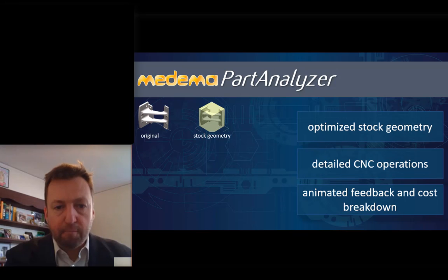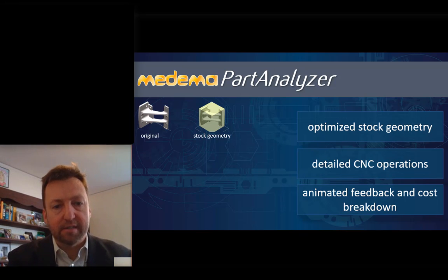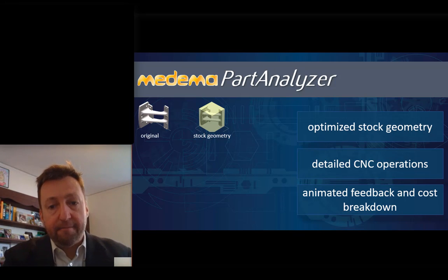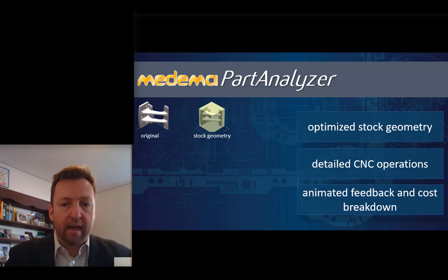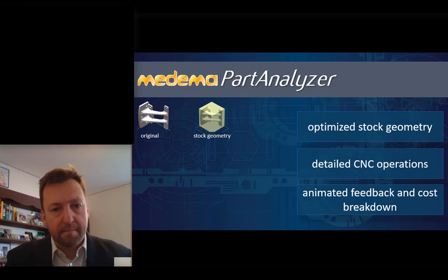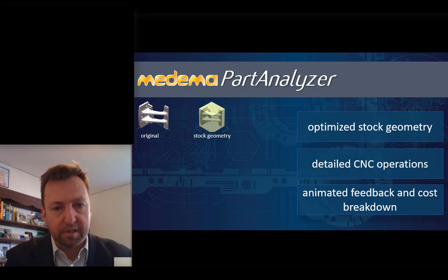So we start with a simple 3D representation of the part, and we'll show you this in more detail in our demo. First thing we do is we optimize the stock geometry. So based upon a lot of stock sizes, we can find what's the best part to start with. And here we have just a green cube around the original part.